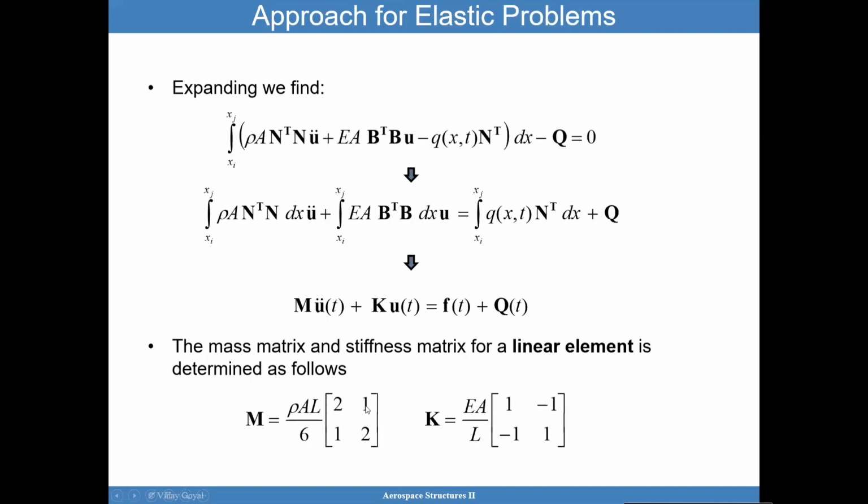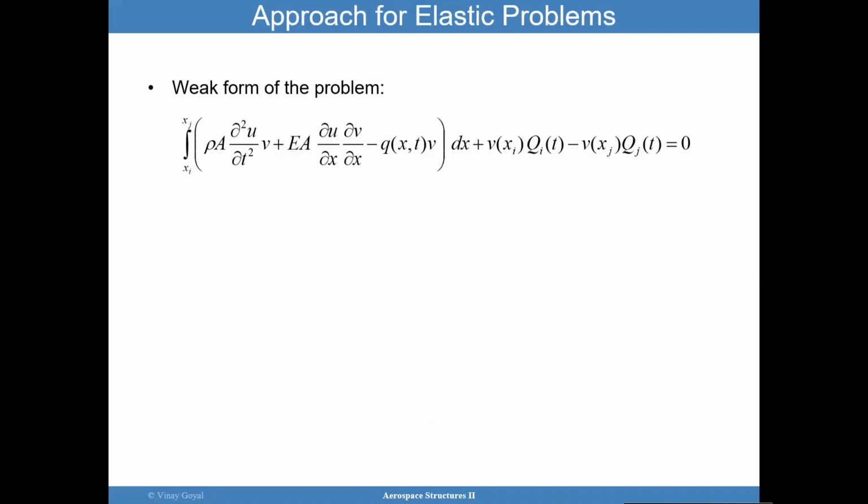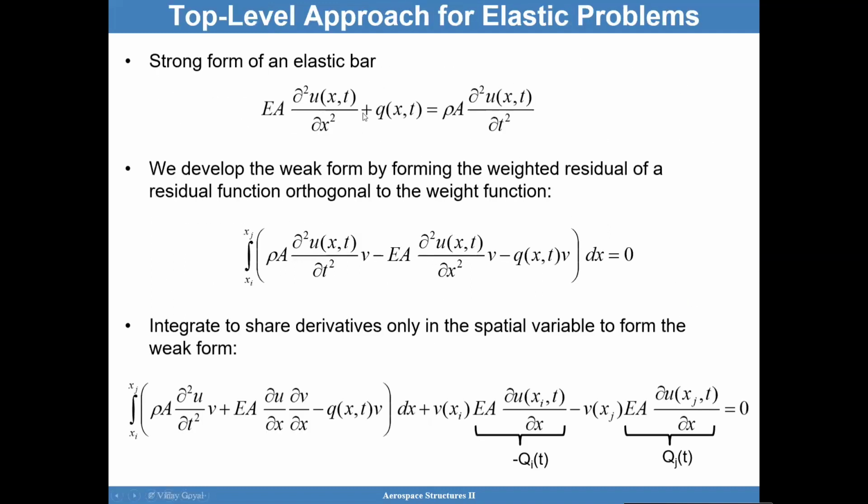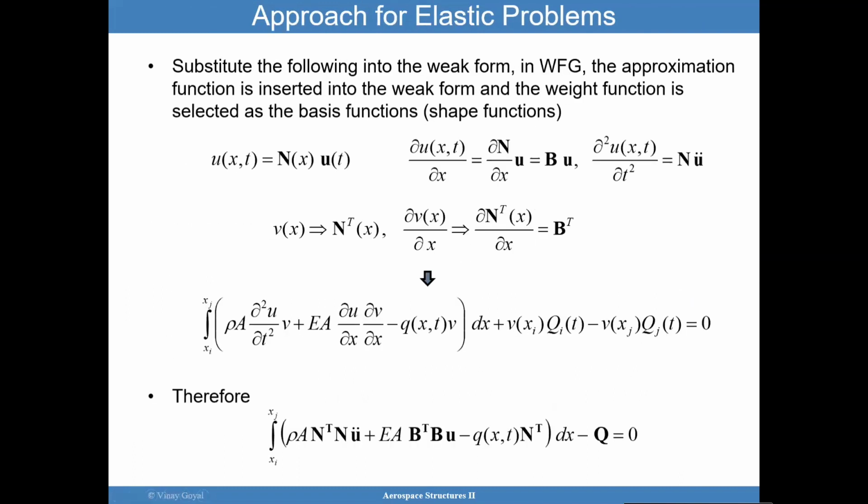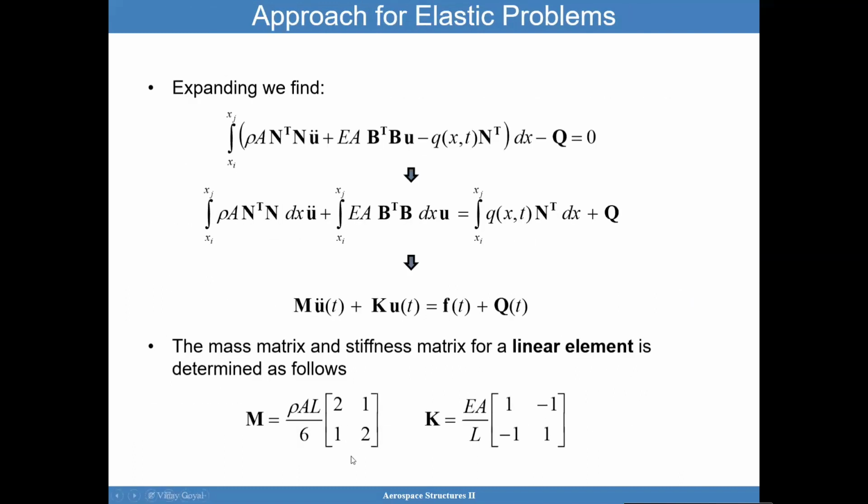And so I have that. I have it for a single element. And the beauty of this, and the point I'm trying to make over and over, is I have taken a fairly complex differential equation, where u, the deflection, varies spatially but also varies in the time domain, and I've shown you how this, for a single element, has been turned into a simplified linear algebra type problem.